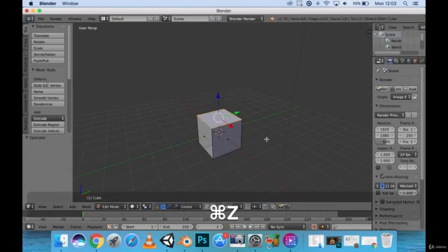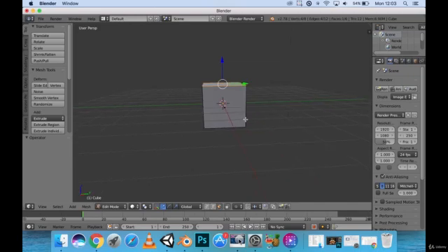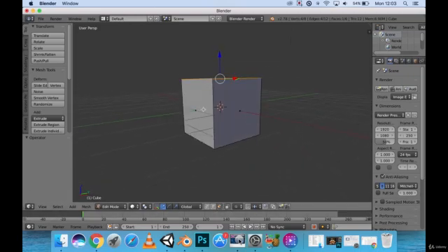I'm going to undo this, and now if you don't want to extrude it, you want to half your cube here, you can simply click Control R, and right now it shows this purple pinkish looking outline here. That's where your edge loop will be placed horizontally on our cube here, or you can set it to a vertical one right here. Any face anywhere right here. It's going to loop around our cube, and so yeah, we're just going to click once.